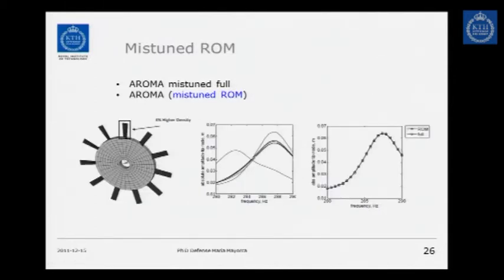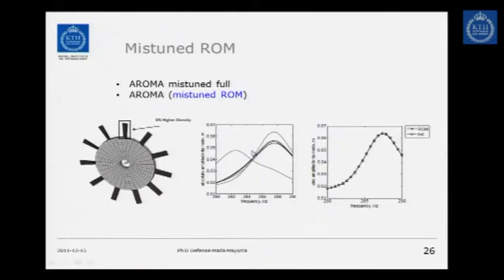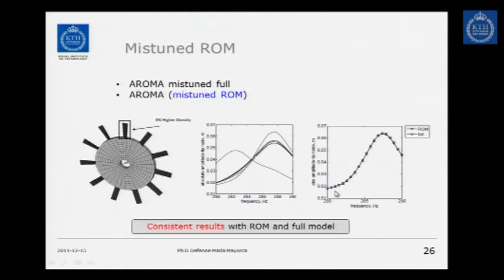The validation for the mistuned reduced model is a cross-validation between simulating a mistuned case with one blade mistuned, doing the reduction model, and comparing with the complete full model with the blade mistuned. So here you see this one blade responding to a specific frequency, and the other blades responding to similar frequencies with different amplitudes. And then this is just a cross-validation between the reduced model and the full model. This is a pre-validation before we assemble the complete BLISK into these models.